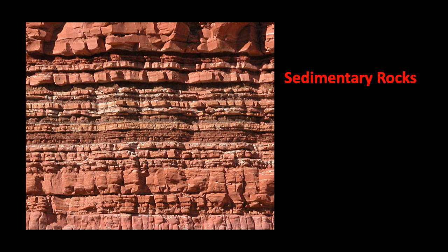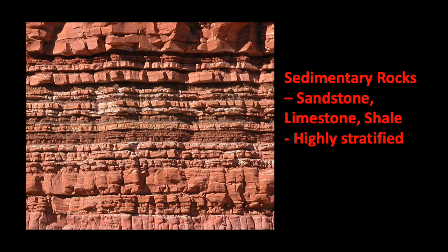Sedimentary rocks can be excavated using the ripping method. Examples of sedimentary rocks are sandstone, limestone, or shale. These types of rocks are highly stratified, which means they are composed of multiple layers. Thus, they are most easily ripped.